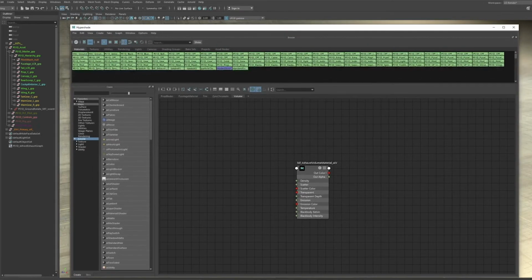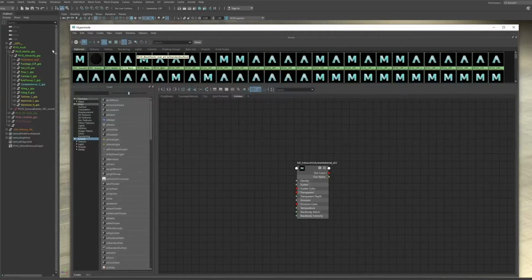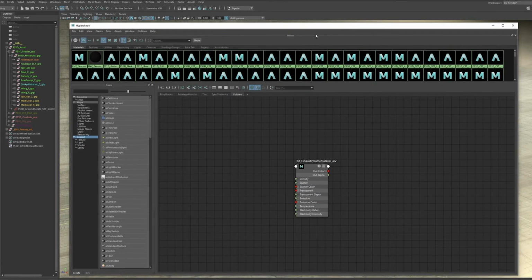So the other thing I want to warn you about, there's this little button here. This is currently set to off. It's usually set to on by default. And if you have these little shader swatches here, this will try to give you a preview of all your materials in the Hypershade. That is slow. And it's annoying how slow it actually is. Since you don't need to see a preview of your materials here, because you will most likely be running the IPR in parallel anyway, and just pause it if you don't need it, turn that off.